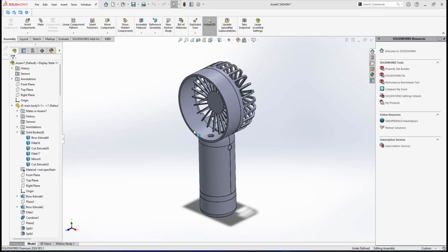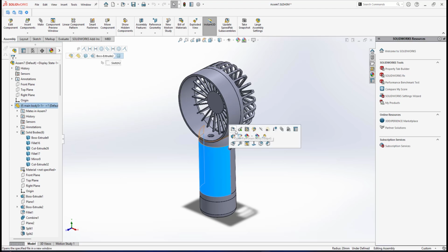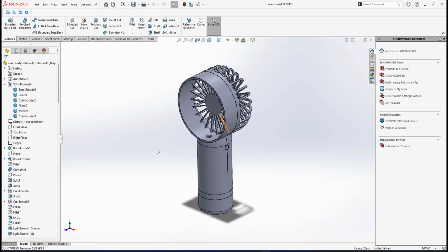Since, as you can see, this is SMD mode. If I open the part modeling mode, so this is a part modeling. Actually, when we want to do the full SMD of our product, normally we will insert one part contains only one solid body. It means front casing only. I will create a separate part file called front casing, while insert front casing only have front casing. So since this is a main modeling of the whole thing, I have 6 components here, so I need to create a separate part file. After I've created separate part file for all my components here, then only I will show you in part 2 how I will do the full assembly.